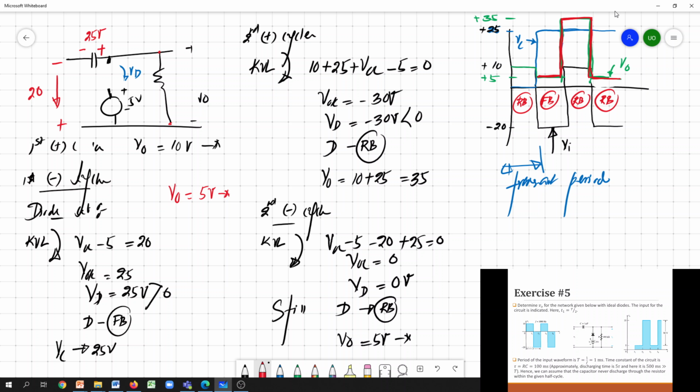So whoever goes through your answer script will be very clear about your knowledge, so you know how to deal with this circuit. This example basically explains the concept which we discussed last time. How do you compare the frequency of the input signal and the time constant of the RC circuit? Depending on these two values, you can decide whether this RC circuit is influencing the charging process of the capacitor or not.